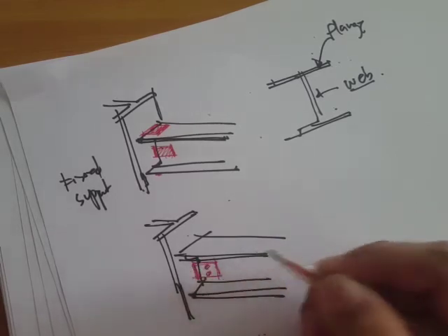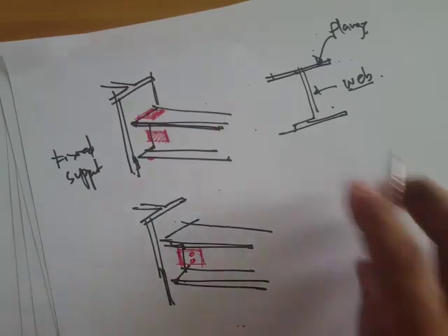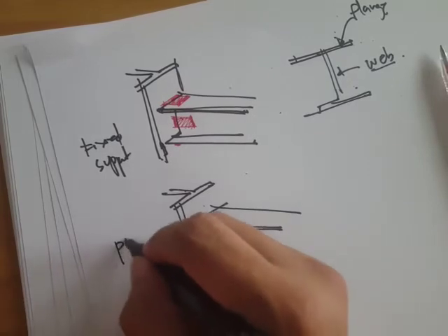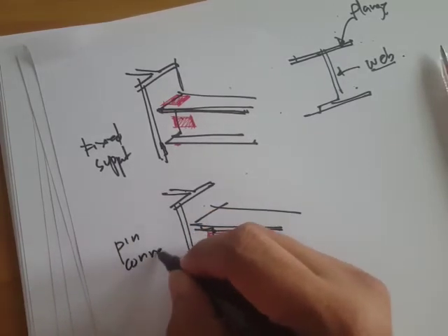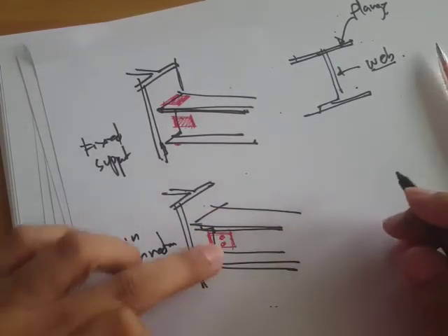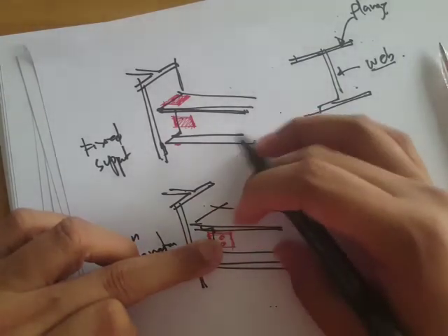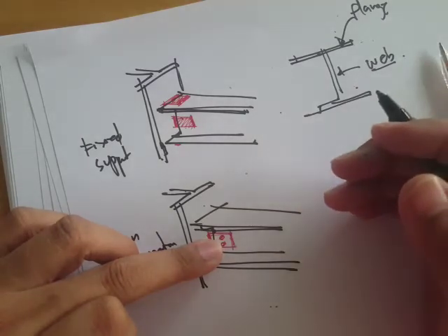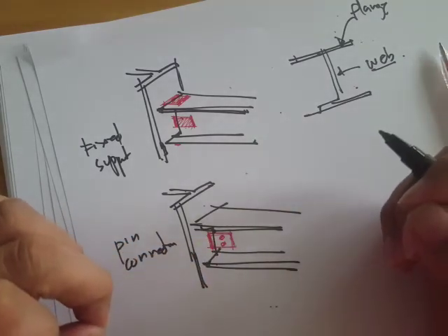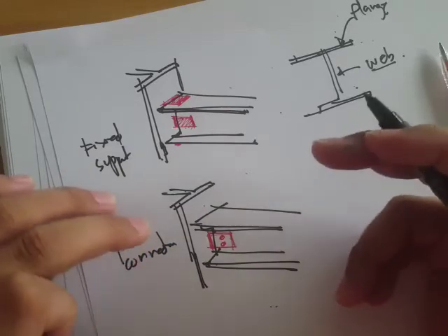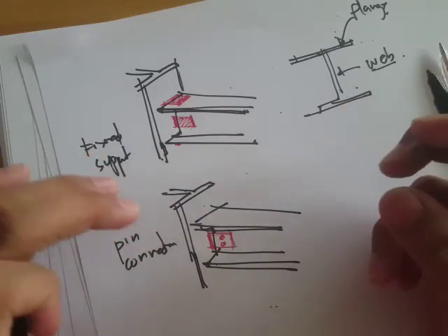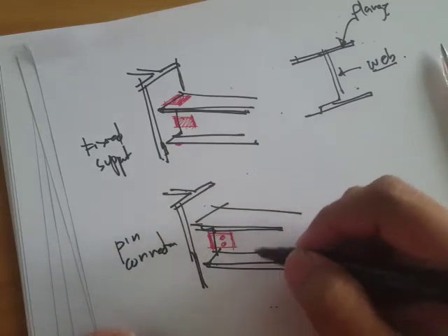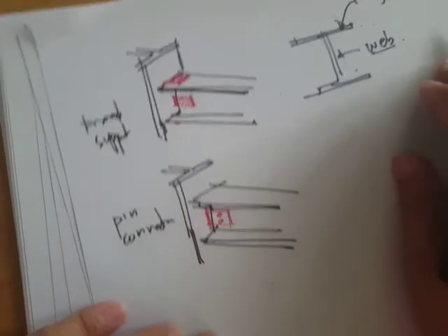Okay, so that's the bolt. This type of connection can be idealized as a pin connection. Why? Because it actually allows slight rotations. So it doesn't have to have large degrees of rotation, but as long as there are some movements in it, probably small movements, then that can be analyzed as a pin connection.